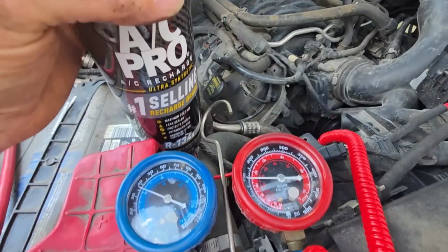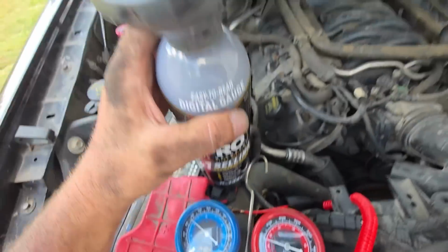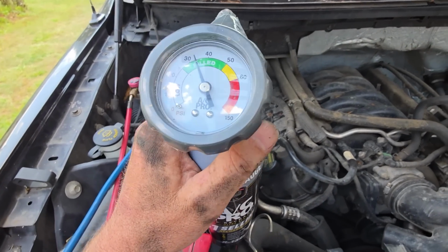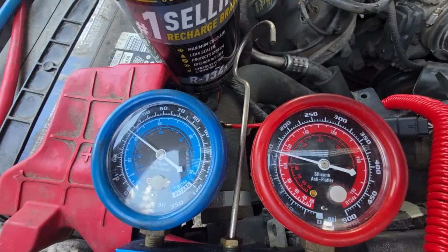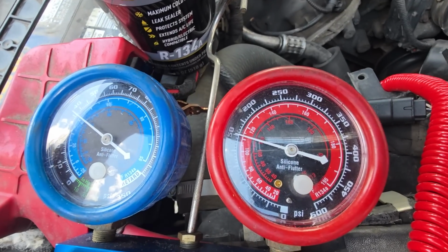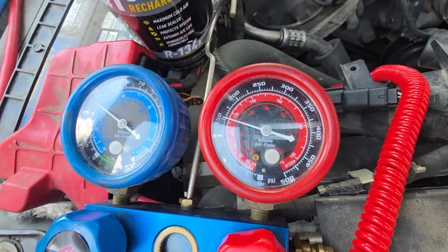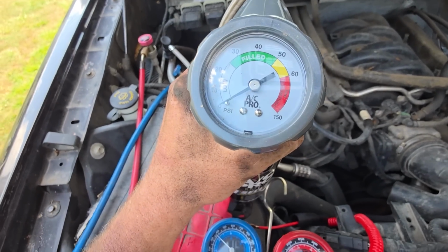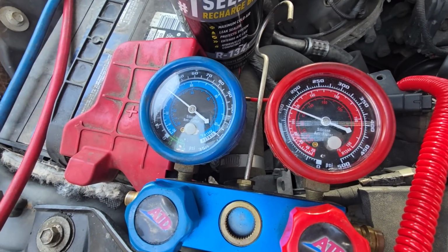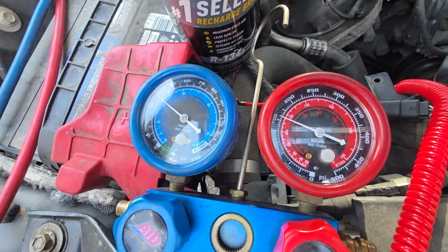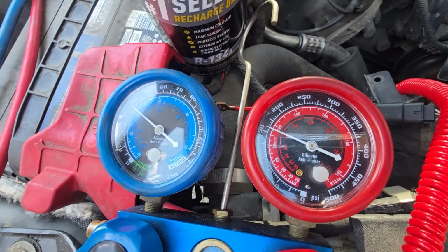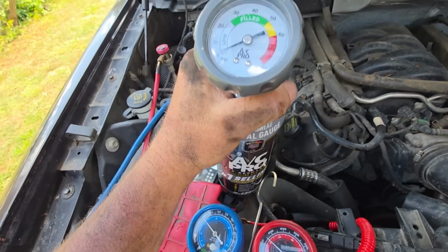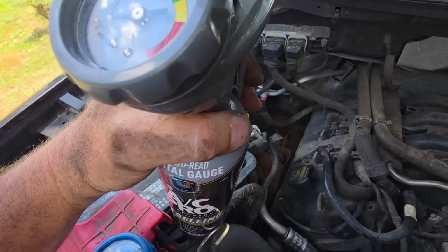Well, we can see both. There's my high side pressure and my low side pressure. Go like 1500. We're really primarily gonna watch our high side when we're adding this. Okay, pulling the trigger, adding some refrigerant. And what I'm watching for, guys, is my high side pressures. I'm adding as a vapor right now. I'm pulling the trigger on this.